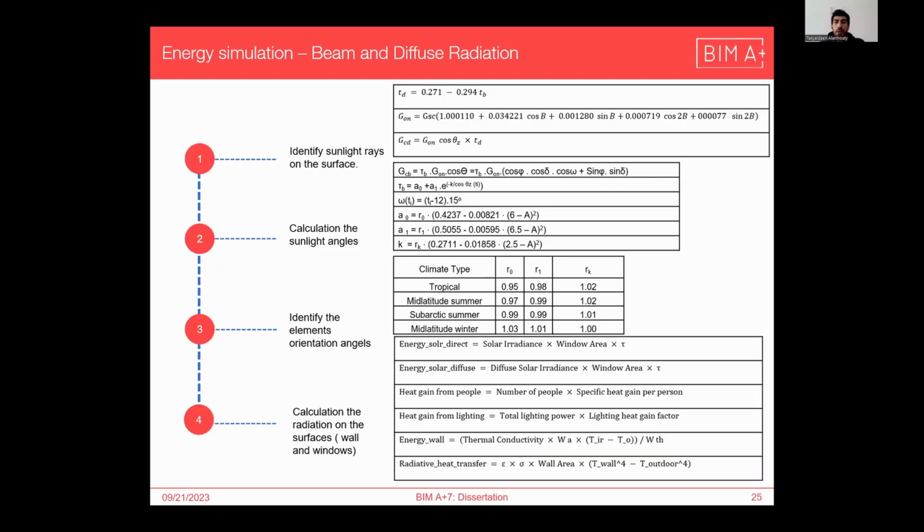After completing the study of the behavior of light and improving it, we study the behavior of the sun in the BIM and the energy gain in the building. The methodology here is by determining the behavior of sunlight during the month and the exposure time of each element separately. Then we study the amount of energy that the elements allow to pass through. At the end, we find the sum of energy gained or lost during the months to determine the amount of energy that must be gained for heating and the energy that must be lost for cooling.